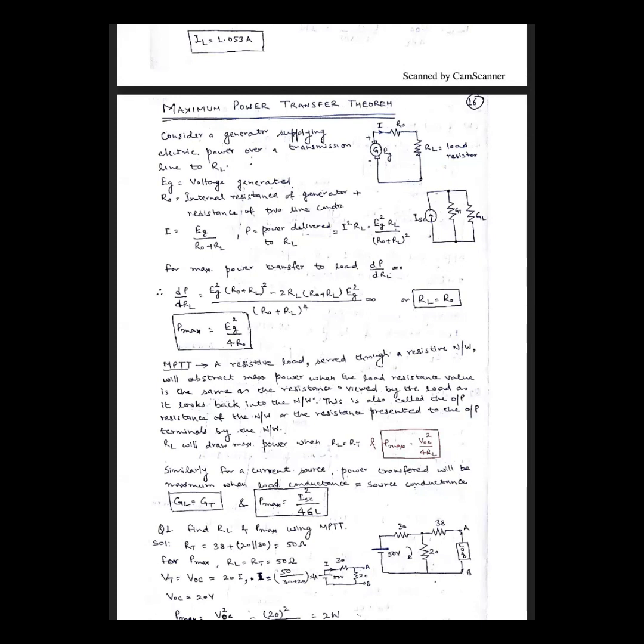So we can say that the circuit can also be changed into this parallel combination of the load resistance, or here this load resistance is replaced by the inverse of the load resistance, which is the conductance. This is experimentally calculated. So again, GT is nothing but the inverse of the Thevenin resistance. Okay, and a current source is there.